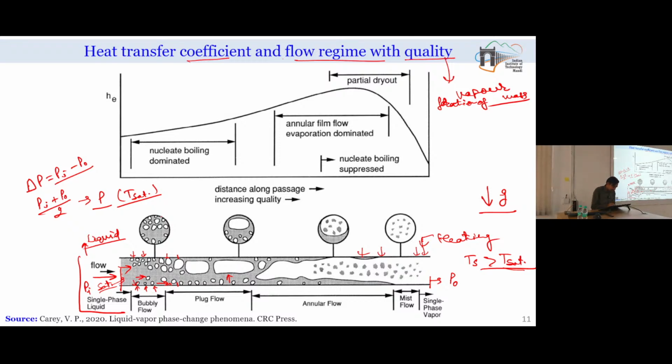And if you see the cross section, here also you can see in this cross section the bubbles having larger volume are staying close to the top, and bubbles which are just nucleating from the tube are available in most portions of the tube with smaller sizes. Similarly, in this plug or slug flow type of situation, we will find that a large chunk of the vapor is staying at the top, but small vapor volumes are nucleating from different portions of the tube wall.